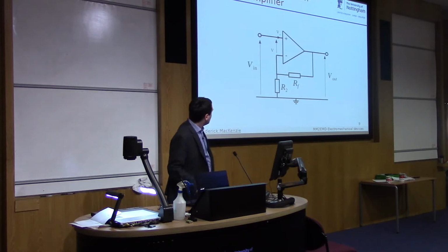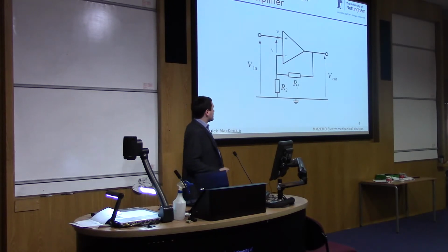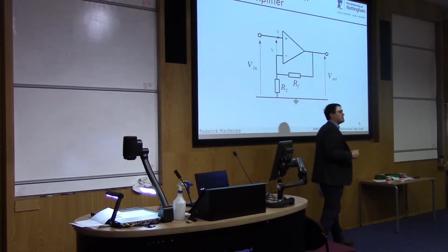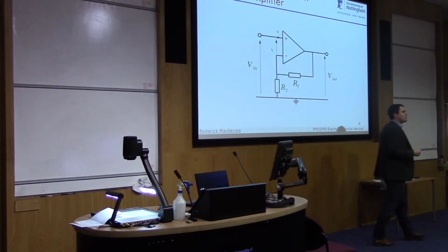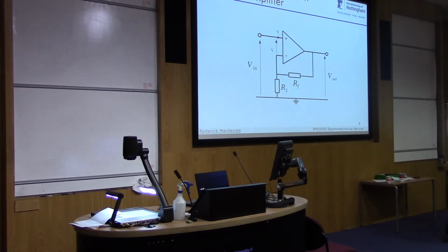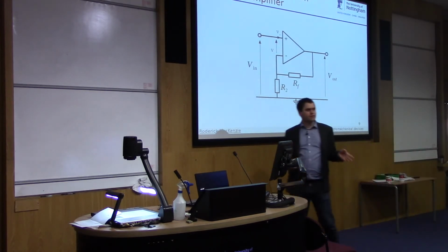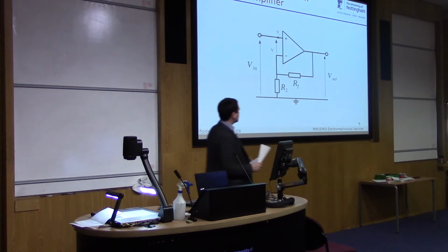Okay? So the other circuit that you've not met yet is this one, and this is called the non-inverting amplifier circuit. This is handy because it doesn't invert signals. So this is the type of circuit that one could potentially use for this audio system here, because it will just amplify the voice. It won't invert it. And they're used everywhere. They're a very, very handy piece of circuitry. If you've got a really small signal you want to amplify, off a microphone or something like this, you can use a circuit a bit like this.